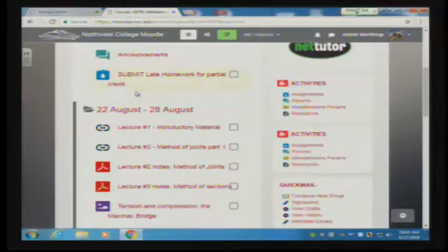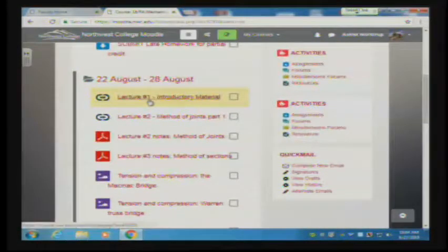Okay? So having said that, the first thing we're going to do is continue and take a look at the method of joints, which is the handout from your page. We've talked about tension and compression. We know that if we're pushing on the joint, the structural member is in compression, and if we are pulling on the joint, the structural member is in tension.